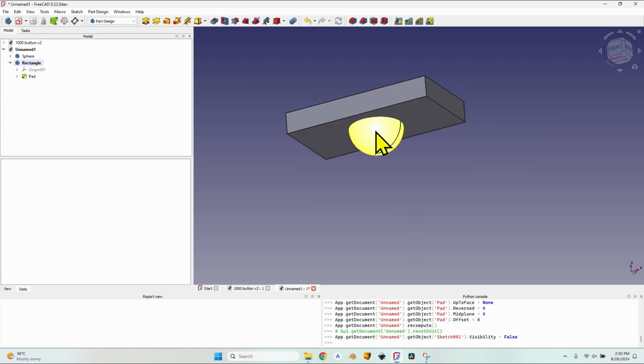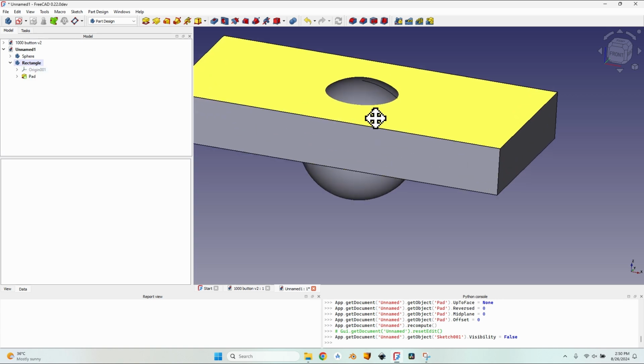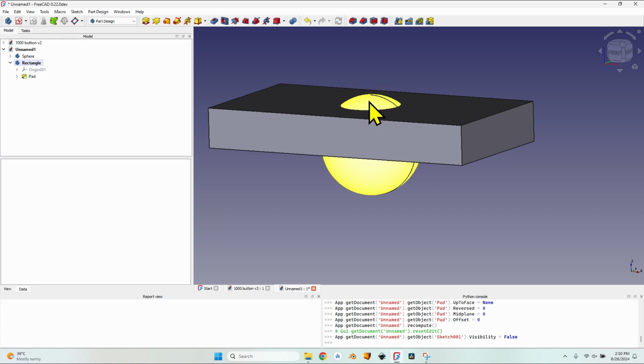and now we have to make the sphere so large that on the top surface of this rectangle I will only have a slight roundover from the top of the sphere. I could have used the Surfaces workbench, but I don't like to use that way because I cannot modify anything. Getting the correct design and maybe adjusting some dimensions and being able to do it along the way without a lot of operations is pretty important to me. That is why I prefer to take the Part Design and Part workbench route all the time if possible.